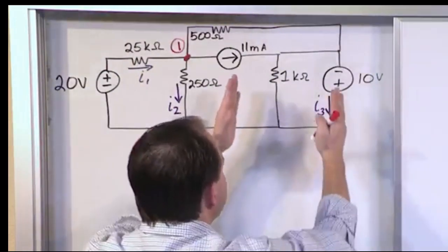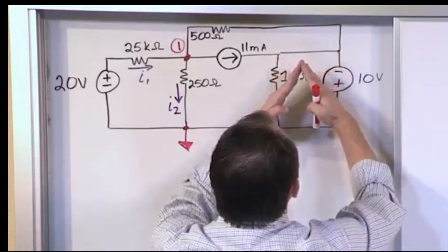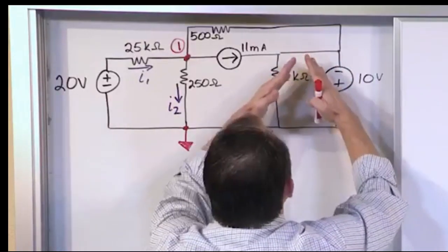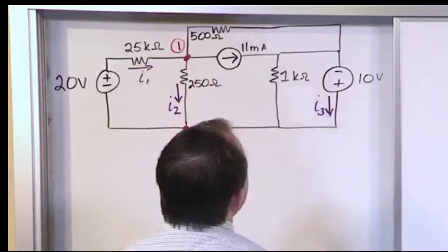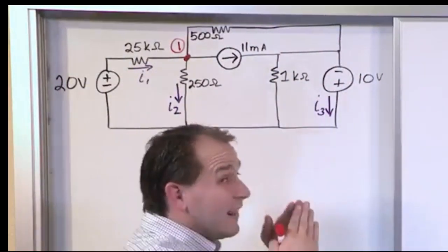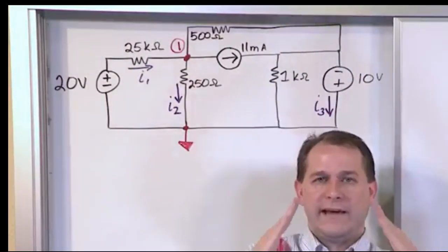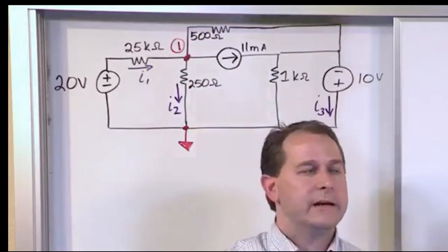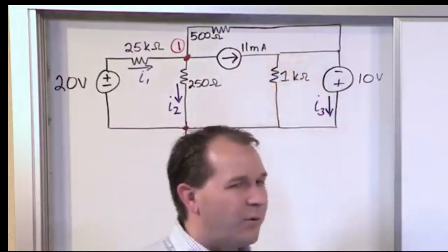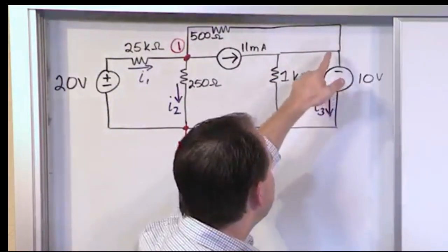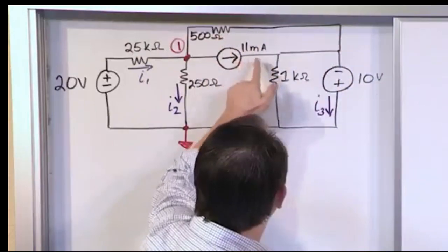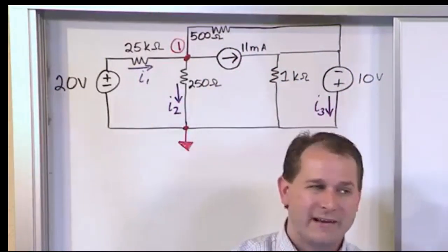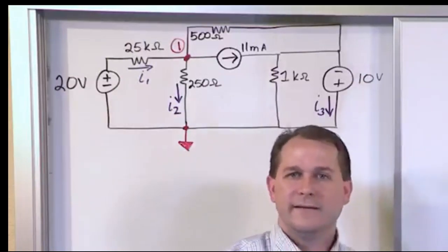If we were to draw them at one point, then I would have to slant everything in, draw this resistor crooked, draw this guy crooked like this, and then join at a point here, and it just wouldn't look very pretty. If I drew it like that, though, where everything came to a point, it would be very easy for you to understand how to proceed, because you would immediately identify this point as an essential node, because it would connect all this stuff here plus all this stuff here at one point, and you'd say, oh, well, yeah, of course that's an essential node. You go and solve the problem like that, right? But it's not drawn like that.